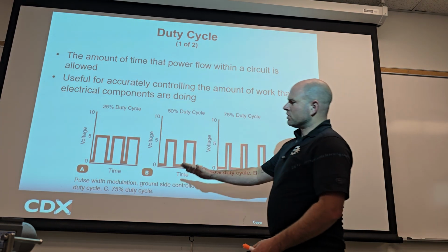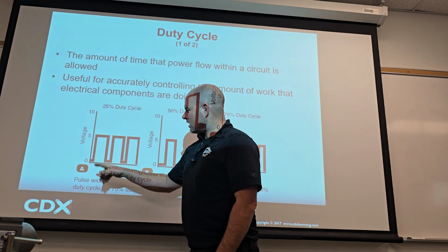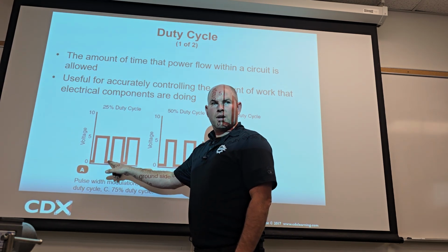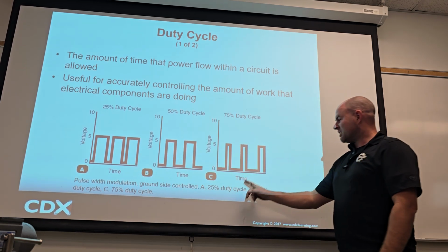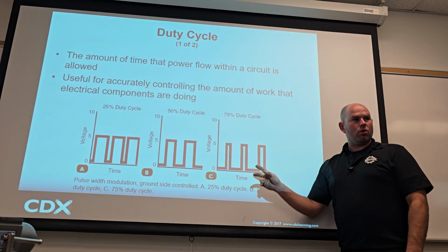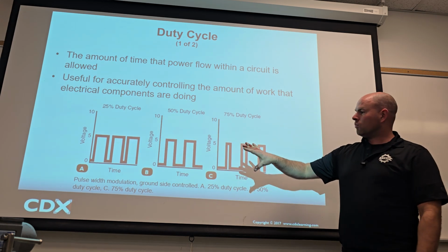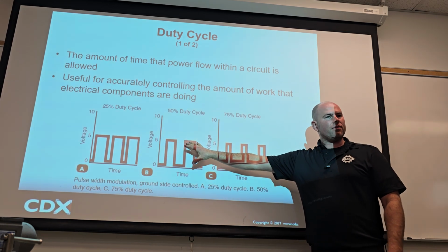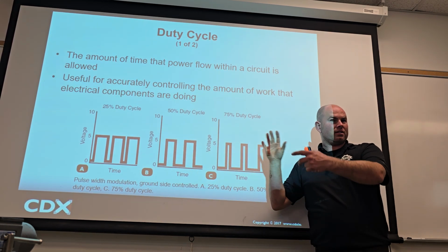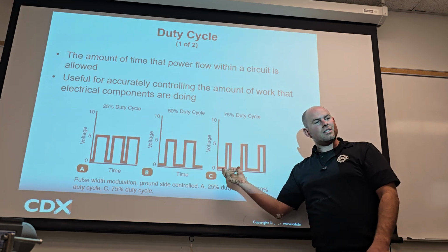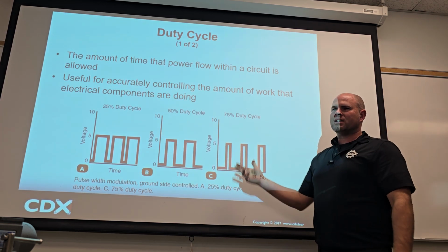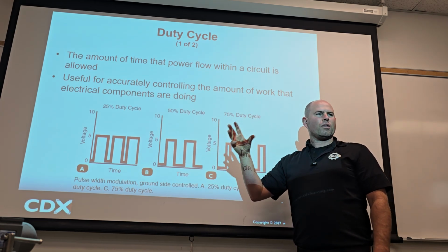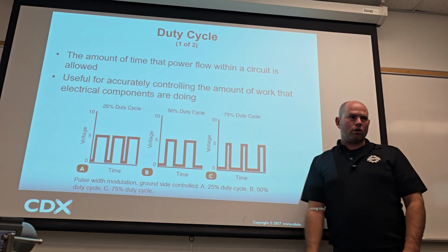Okay, so now when we're back over to here, I'll show you on this picture. This is actually pulsing the ground. So if you're really looking at this, you see your ground is pretty short right here. Isn't this more ground right here? Isn't this the most ground right here? So you'd actually have to go in and graph this to see if it's getting ground in the right distances, not just 0 volts. You put your meter on here, it may say 0 volts, but it may be jumping all over the place.